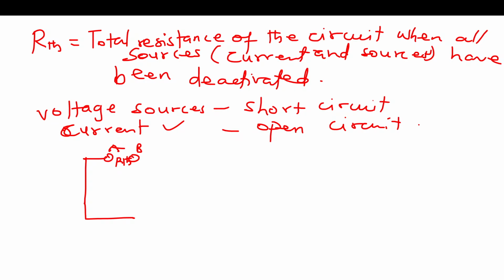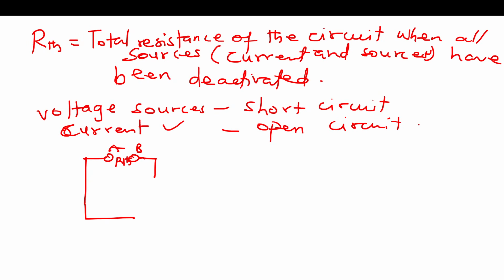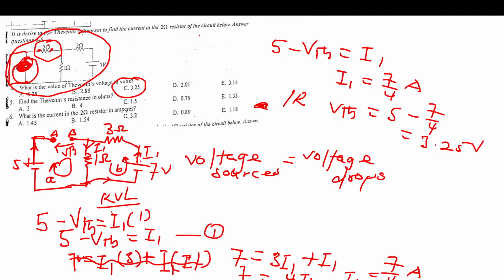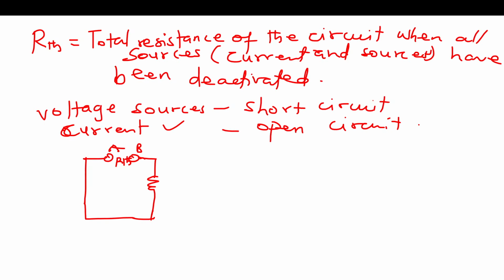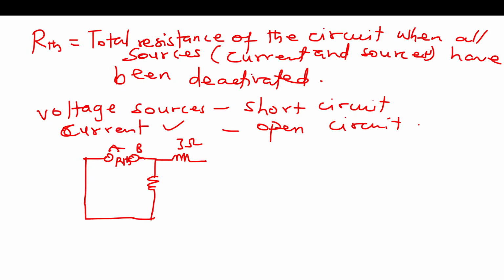Okay, when we get to the 1 ohm inside there, we are still going to bring it because it's not affected. All right, now the next 3 ohm resistor here is also not affected. But guess what? When we get to this part, we are going to short circuit it. So it's going to take away this. So essentially, we are going to continue this way and then back. So this is how our circuit is going to look like.